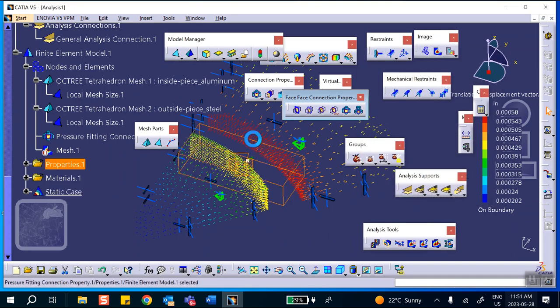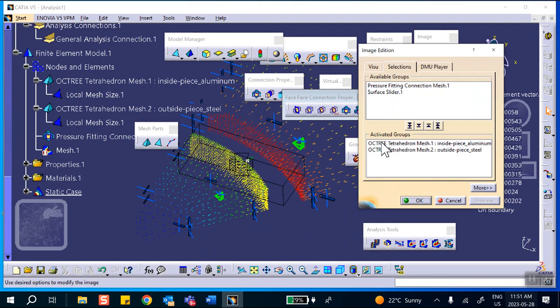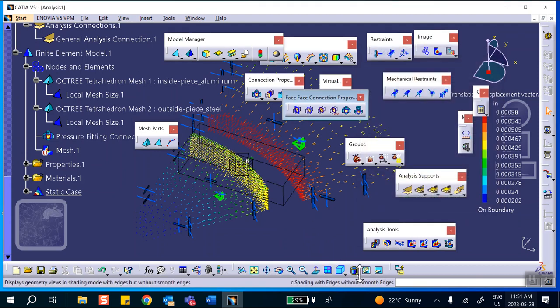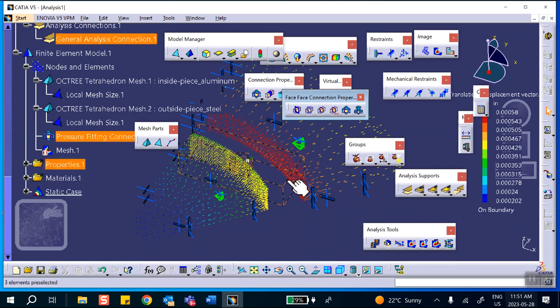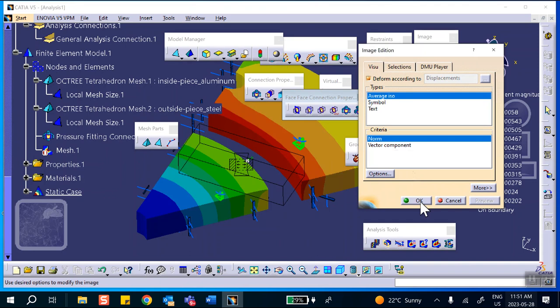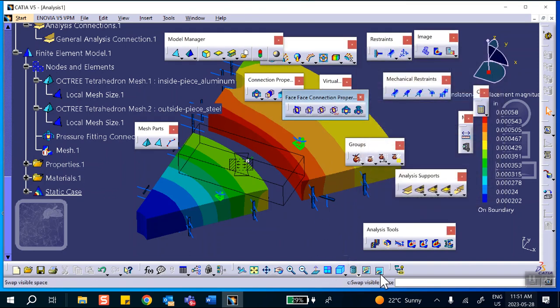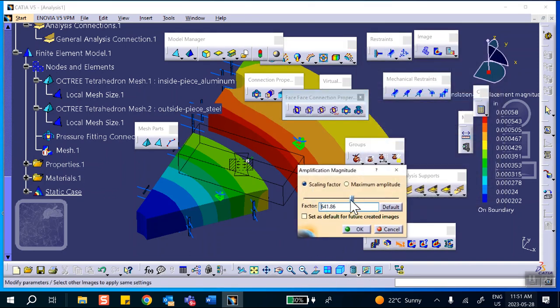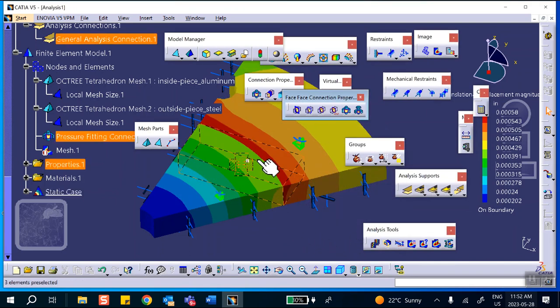And then double click, actually just change the rendering to material shading, and change the scale to 1 so that you don't see that artificial gap there, which is an artifact basically.